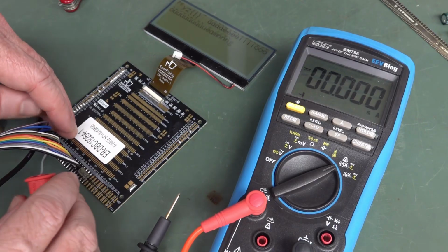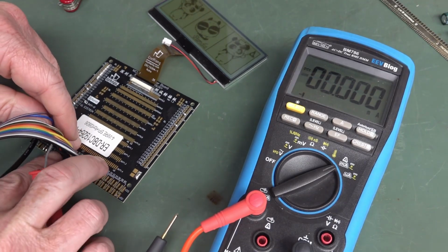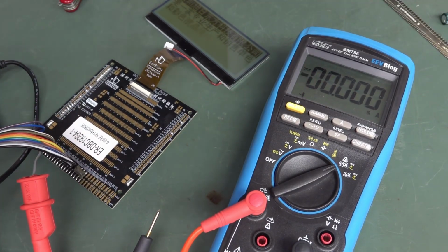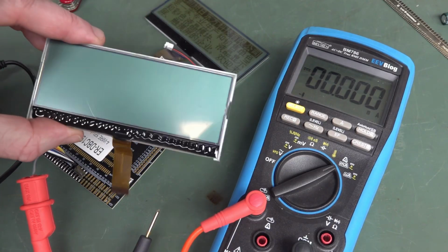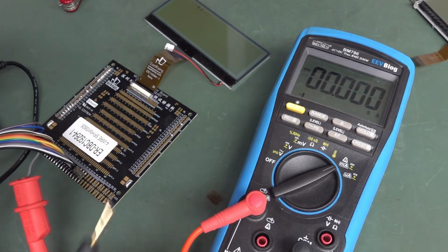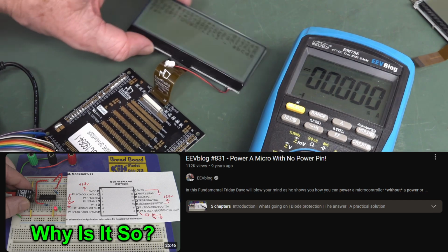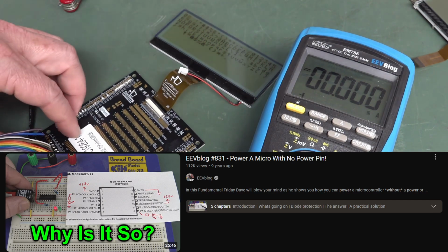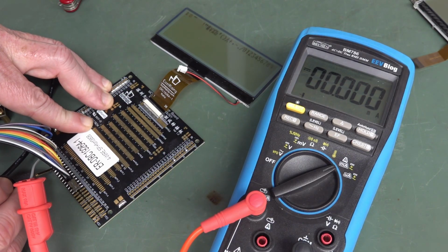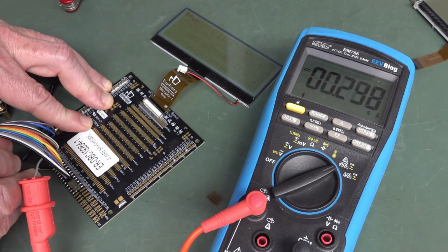Bonus. Well, I've got the correct power pin now, which is pin 19 down here, and which is offset by 4, because I got the data sheets goofed up because I have another display here, which is completely different, which I might show you later. Anyway, you can see that it is actually working with no power pin, because I've done a video on that, and I'll link that in. But let me now plug in the power pin, which will override it being driven elsewhere. There we go, making contact, 280.